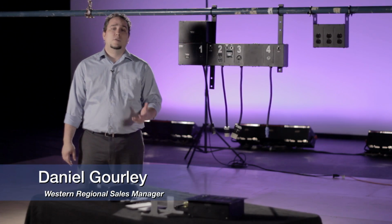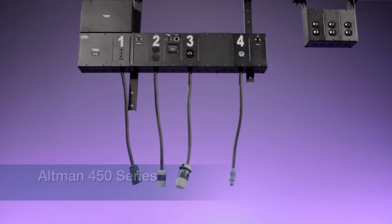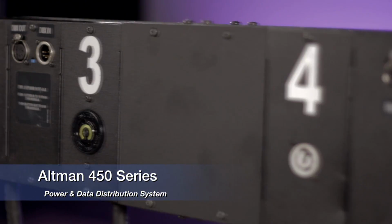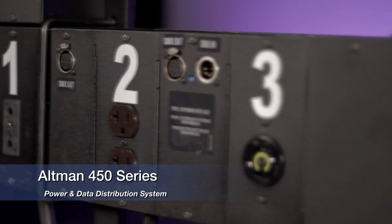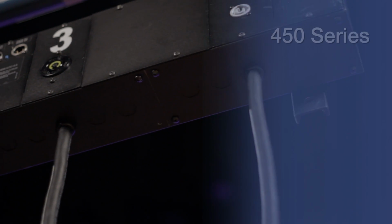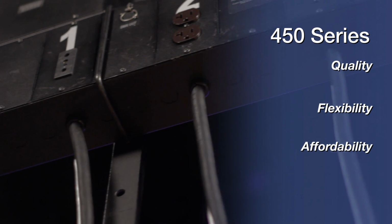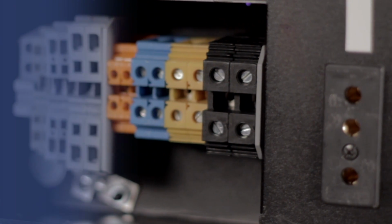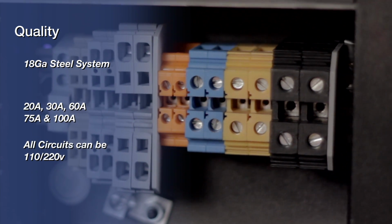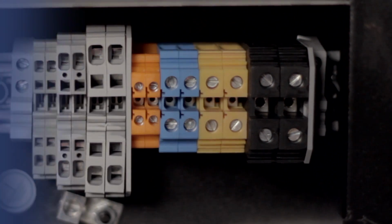And today we'd like to show you our 450 Power and Data Distribution System. The 450 Power and Data Distribution System is the most innovative and forward-thinking system available from any theatrical lighting manufacturer to date. The 450 distro is based around the ideas of quality, flexibility, and affordability that can satisfy the most demanding of applications. Altman Lighting's 450 series is an 18-gauge steel distribution system that can house 20, 30, 60, 75, and 100 amp 110-220 circuits.